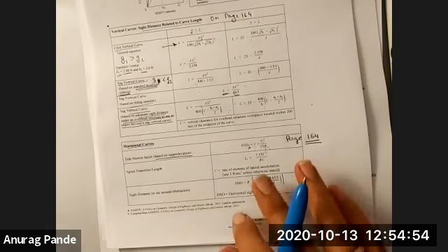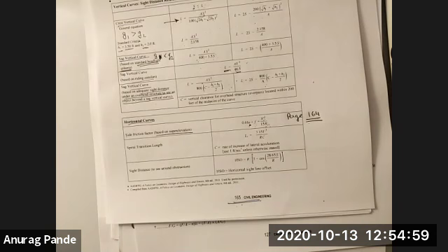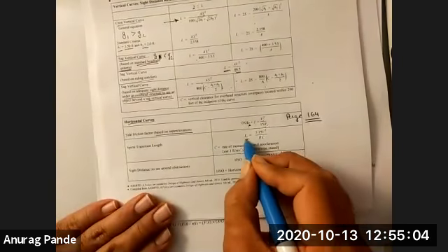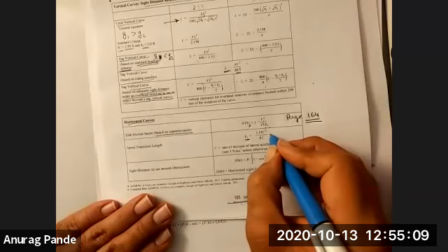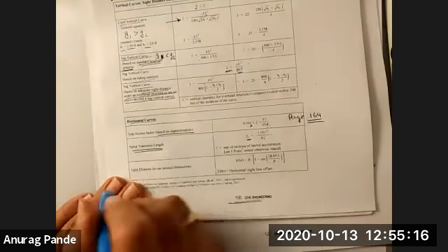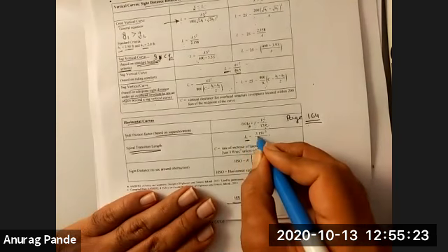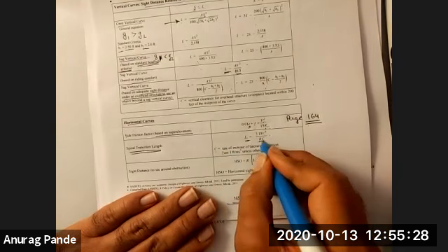Now, one thing that I told you that we might not be considering, at least for design purposes, when we were discussing the horizontal curve design, was the length of the spiral curve. That's the transition into the circular curve. This is just a simple formula. I don't expect you to be asked to design a complete spiral curve, but they might ask you how much transition length might be required to go from a straight section to a fully circular curve section. So Ls would be 3.15 times V cubed over RC, and all these parameters will be given to you in the problem.